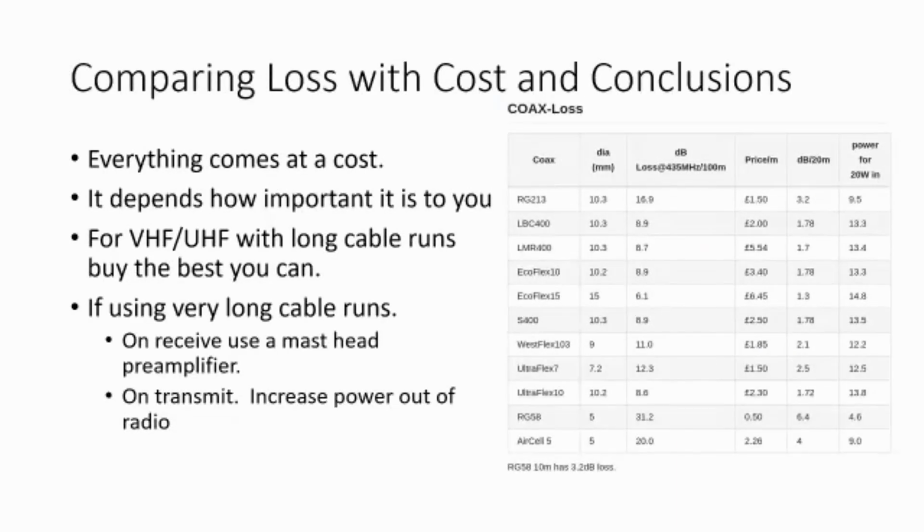So one of the things we need to do is compare the loss with the cost, and everything comes at a cost. Some of these cables can be very expensive. It depends on how expensive it is to you. For VHF, UHF with long cable runs, you really want to try and buy the best you can. If you're using very long cable runs, you might want to consider a masthead preamplifier on receive, and you might want to increase your power output of the radio on transmit.